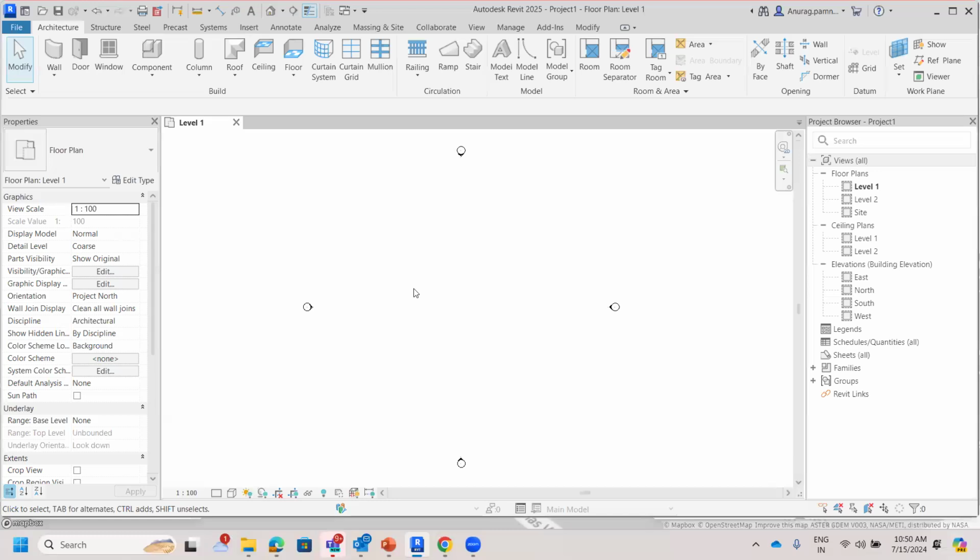सेकेंड थिंग, अब हम प्रोजेक्ट पे आते हैं कि अगर मुझे G+2 रेसिडेंशियल बिल्डिंग बनानी है या कुछ भी मुझे बनाना है, so first thing I am going to decide is at what levels the things are going to be. तो अगर मैं शुरुआत करता हूँ कि नेचुरल ग्राउंड लेवल is 0 0, then मेरा plinth level is at 450 or 600, then I will be having my ground floor का slab at 3300, something like this.